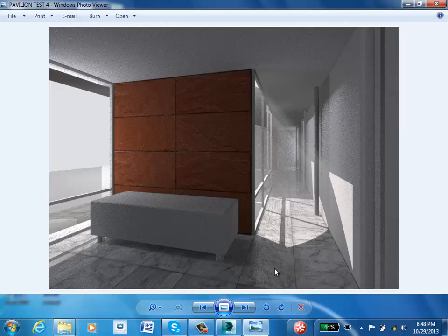Let's say you don't mesh it individually. When you create an OBJ file, it automatically meshes the object because that's really the only way 3ds Max will understand it. So it's not like you can import those objects as solids into 3ds Max. It will only understand it as a series of meshed surfaces. So as you convert it to an OBJ file, it's automatically going to convert it into a mesh for you.